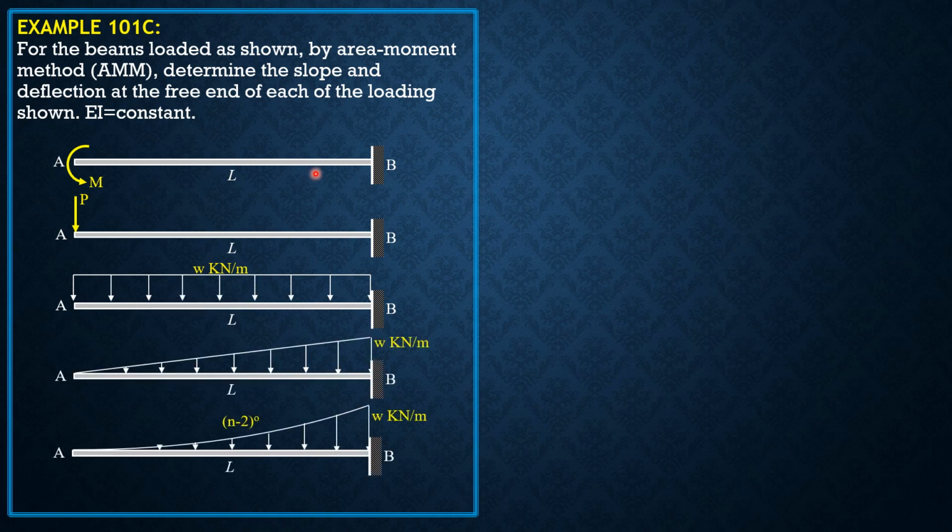So for the first situation, this is the beam and the moment diagram by parts. We have the tangent at B, the tangent at A, and that's the angle theta. This is the deviation of point A relative to the tangent at B, which is horizontal. So the deviation of A relative to the tangent at B is automatically the deflection at A also. This is the moment diagram by parts. This is negative. The horizontal line is here.